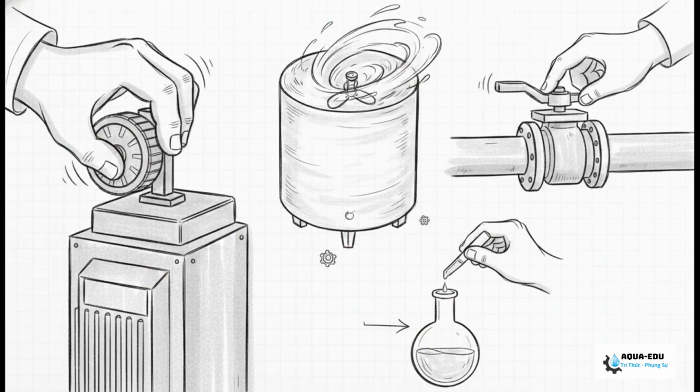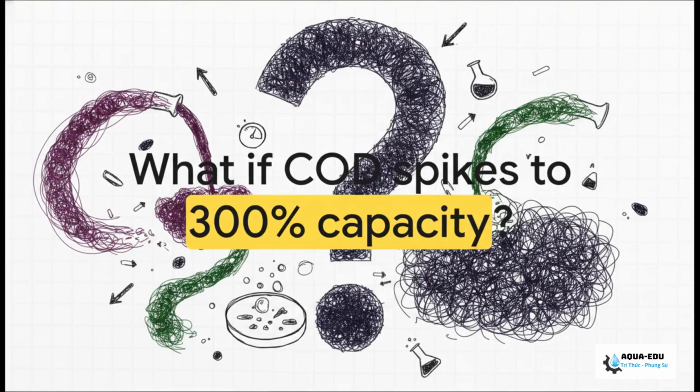You must instantly manually override the dosing pumps to push base chemicals like sodium hydroxide. Crank up the mixing in the equalization tank to its absolute maximum to spread that chemical out fast. If the pH rockets above 11, completely cut the influent flow. Keep your dissolved oxygen above 2.0 and take samples every 15 minutes like clockwork until that tank stabilizes between 6.5 and 7.5.